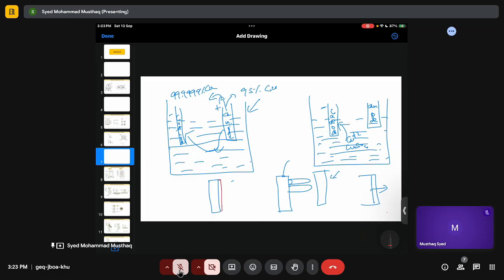This is at time t1. After time t2, the thickness has gone up by this much, and after time t3, the thickness is uniformly growing. But here it is not the case. Because the thickness is not uniform, these guys grow so large that they actually touch the anode. So this was my cathode. Whenever you touch the cathode and anode, that is nothing but a short. So that means you have created a short circuit.